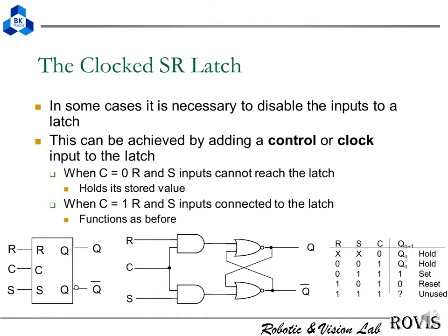And we have another thing we call the control. The control here is something like a don't care signal. For example, you can see on the truth table that when C becomes 0, the R signal and the S signal don't care. They just keep the previous value.